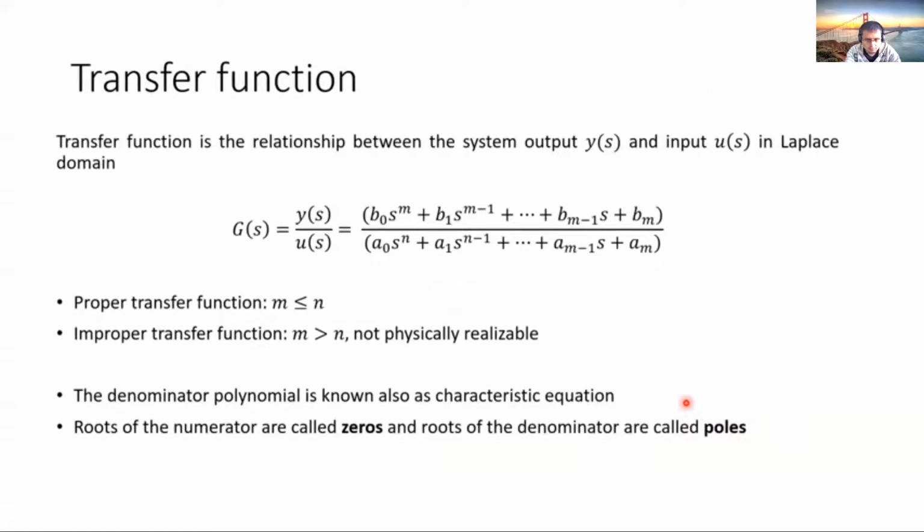Okay, as we saw in the previous lab, we are using the transfer function representation to work with LTI systems. The transfer function representation is easier to analyze or understand in the frequency domain. The transfer function is given as the ratio between the output and input of your system.